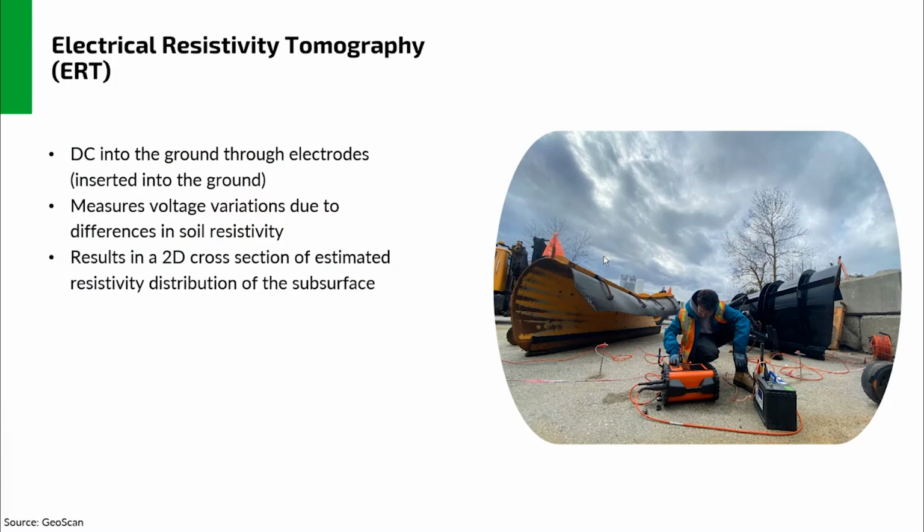through certain electrodes. In a single channel mode, we are using 2 current electrodes and 2 voltage electrodes, where we measure the potential differences, and using some relatively simple calculations, we can calculate the apparent resistivity at every single point for every single electrode combination. Once we have calculated the apparent resistivity, through geophysical inversion we can estimate the resistivity distribution along the survey line.